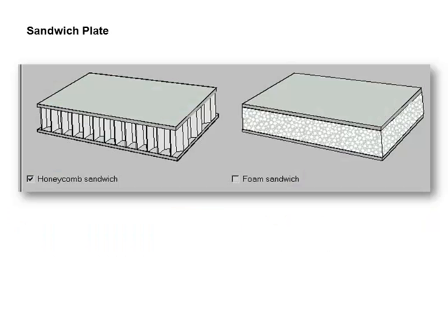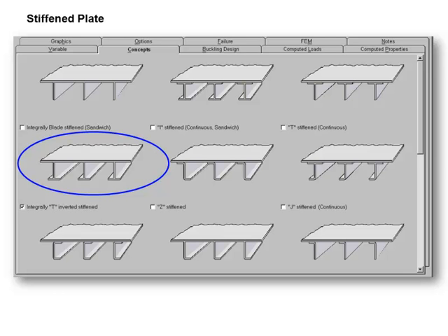In Hypersizer, you have the option to select as many panel concepts as you choose to be considered in the optimization. Without changing the mesh, all of the panel cross-sectional dimensions and plate thicknesses are optimized to the loads from the ship FEM. Hypersizer will determine the lightest possible design for each selected panel concept and report their optimum design dimensions. In this way, the best structural design for all locations of the ship hull can be established.